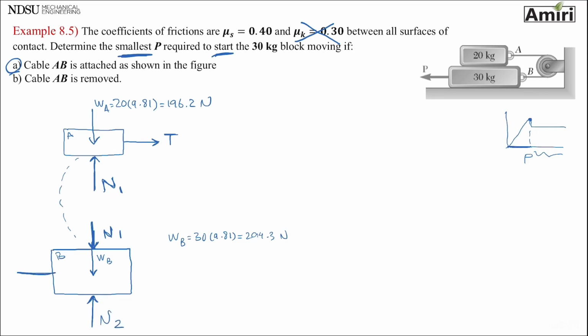It has a force P going this way. It has a force T going that way. I've seen a lot of people put T1 and T2, and then there are too many unknowns, they can't do it. Remember, this is the same rope. Same rope, so it has the same tension all over. So they're both T1. All right, now friction.